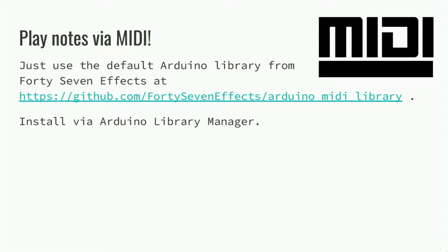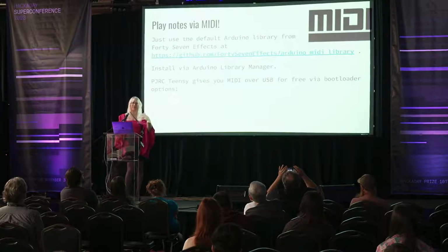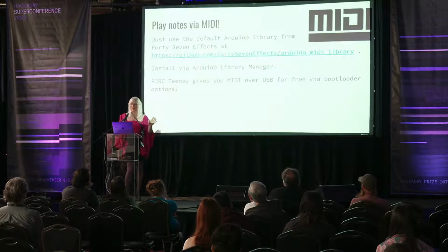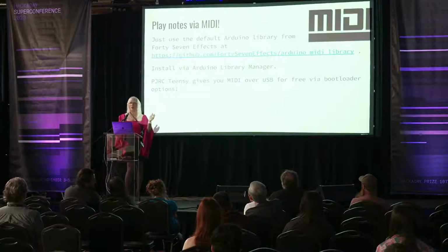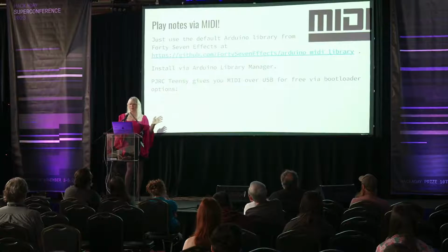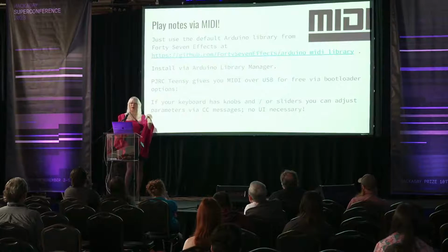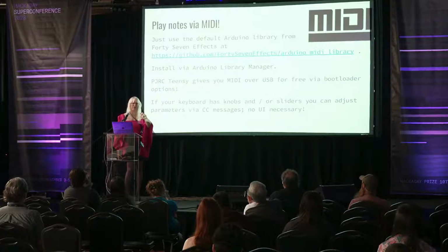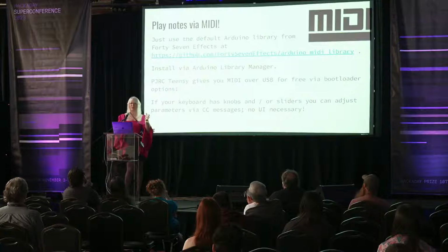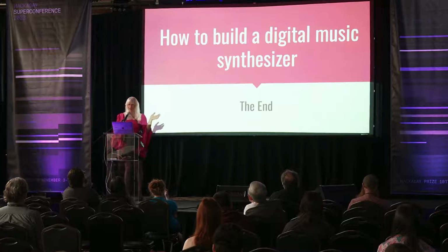There's a nice MIDI library for Arduino, which is in the library manager. PJRC, which makes the Teensy chips, which are really great for doing audio projects, gives you MIDI over USB for free with the bootloader. I don't know if that's a thing on Arduino yet, but that's really handy. That makes things trivial. And then if your keyboard has knobs or sliders, you can adjust your parameters with CC messages, as I was saying. And then you don't have to actually have the knobs on your own box. I like to have the knobs on the box. Knobs are cool. So that is the end of the talk.